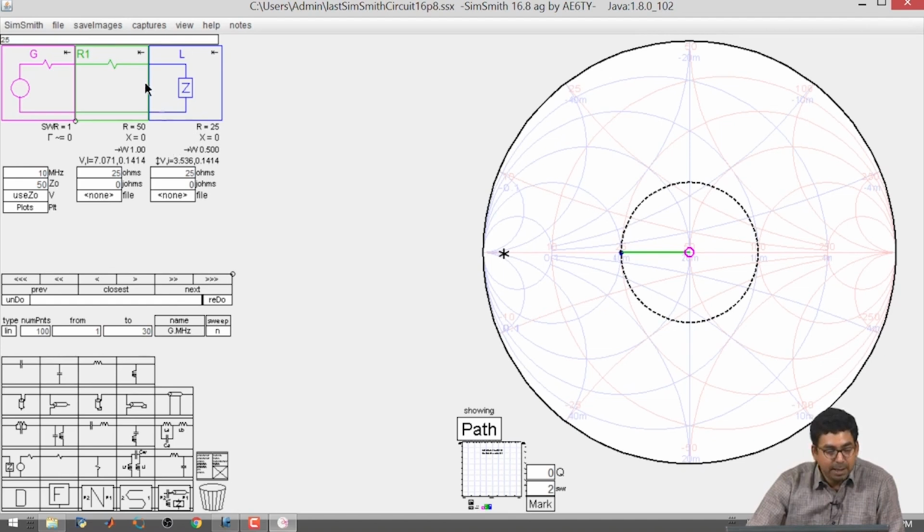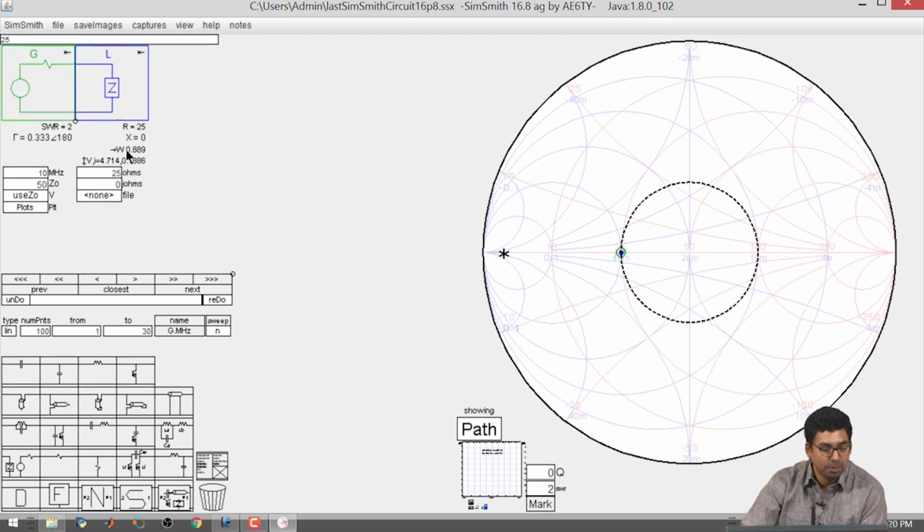So, what we are seeing is if we add a resistor in series, it is going to draw some power, and under the impedance matched condition, it is going to dissipate some amount of power. Now, this particular example assumed that your load resistance is less than the intrinsic impedance of the generator. So, you could add a series resistor. So, let us go ahead and remove this part again. We will make our load resistor higher. Previously, we had half, now we will make it double.